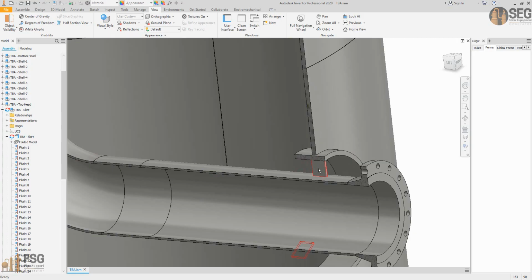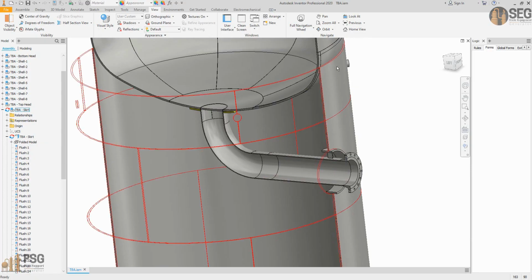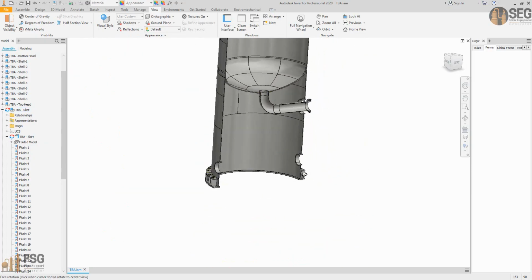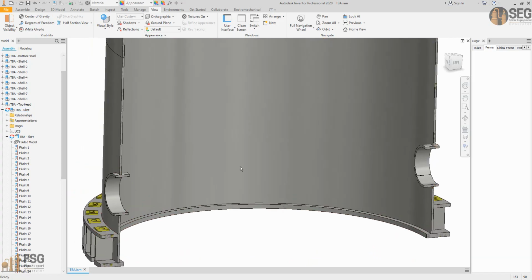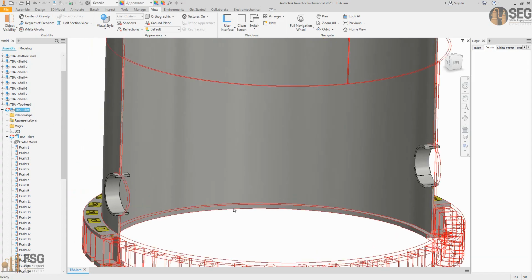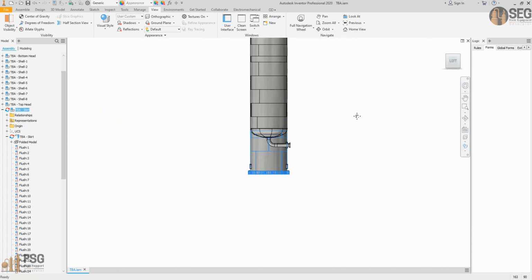After that, we add stiffening grips for that nozzle inside the skirt opening. We add 4 skirt vents, and we learn how to make a copy from a part and add it to the same parent.